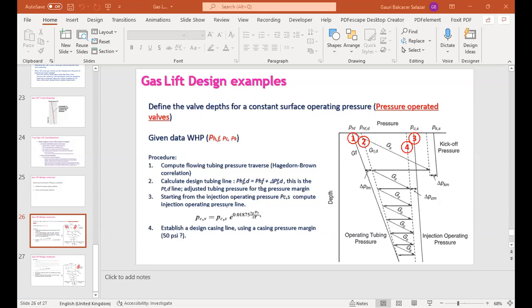We see that increasing the rate from 1 million to 1.007 million, which is the one we defined right here, we are not really gaining any big difference in the production, only 12 barrels per day. So the idea is then to use 1 million, and we are saving costs, we are compressing less gas. In this way we have defined what is the optimum gas lift ratio.